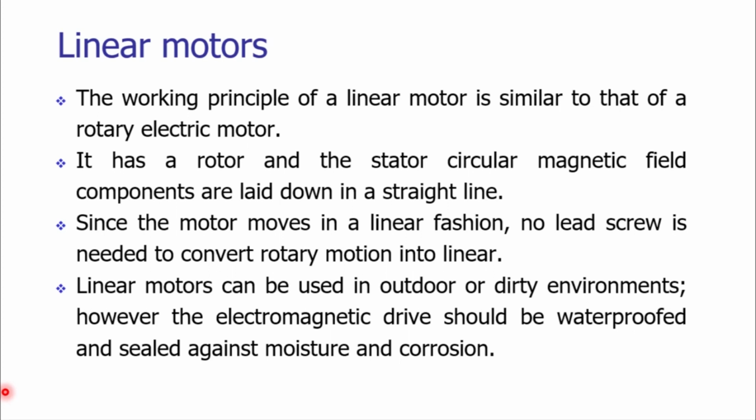They may malfunction when they are exposed to moisture or corrosion and dirt in the environment. We need to have the waterproofing of this equipment. We need to have the proper sealing of the linear motors to protect them from dirt, dust, moisture, and corrosion.